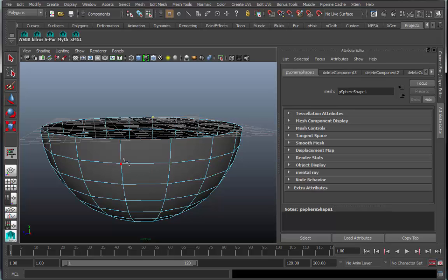Now, you need to make sure you do this before you begin. Hold down the Shift key, because with the Shift key down, you now see the word Snap coming up, and that means that this is going to snap exactly in the middle of an edge. So you're assured a very clean bifurcation of the edge exactly at its midway point.